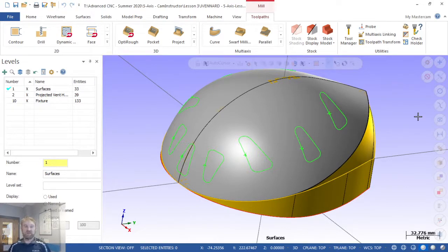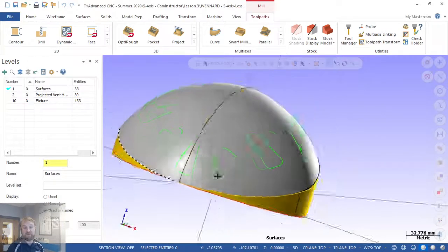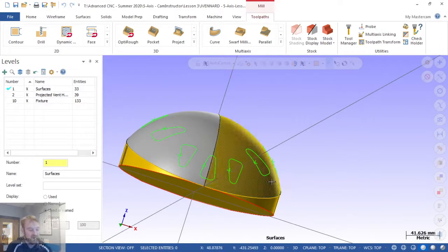see there. So this is a pretty common 5-axis toolpath that you would use when you're doing stuff like this along a surface. I've seen a lot of parts from companies like Flying S that make stuff for Tesla and things like that, and other aerospace companies where they've got very thin parts with pockets and gaps in them. And this is the type of toolpath that they're using to do that on these curvatures that they're working with. So this is a toolpath you very likely, if you end up in a 5-axis environment, will use